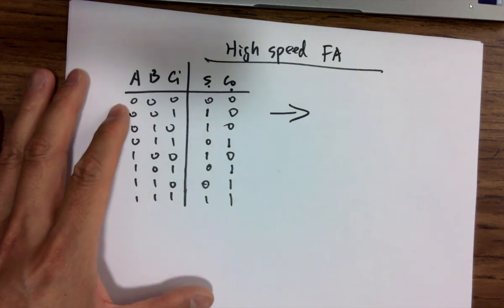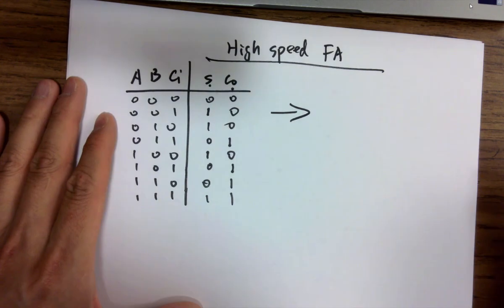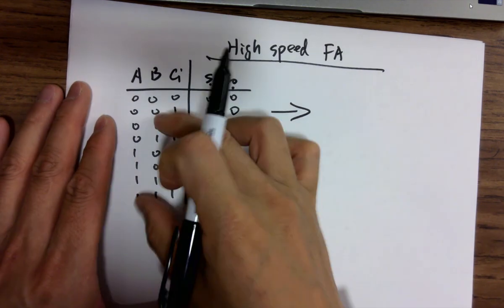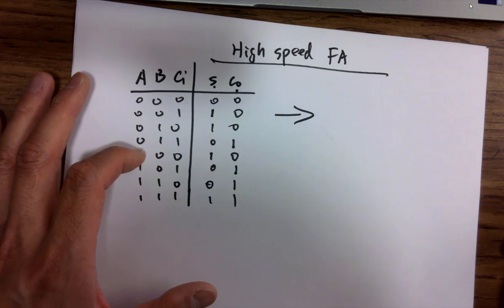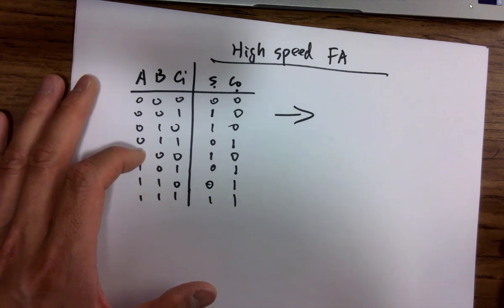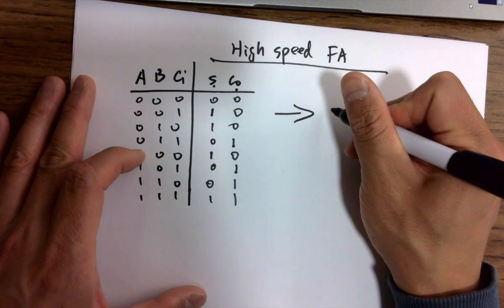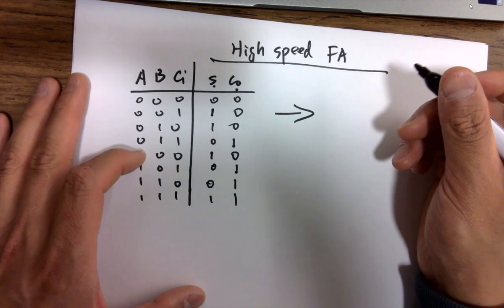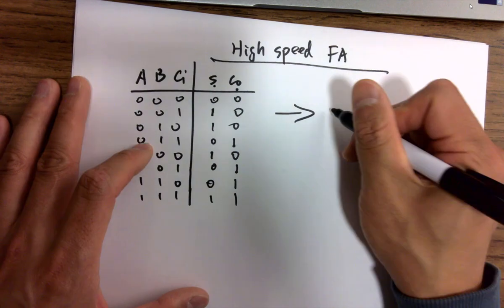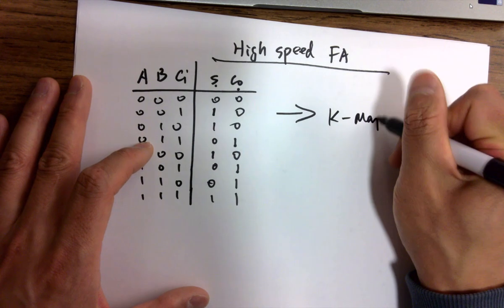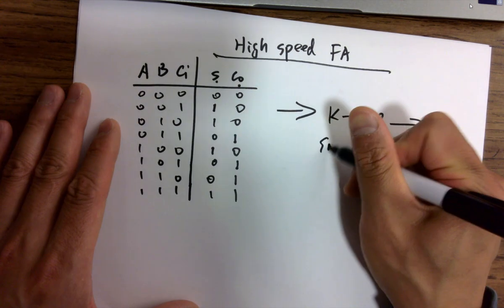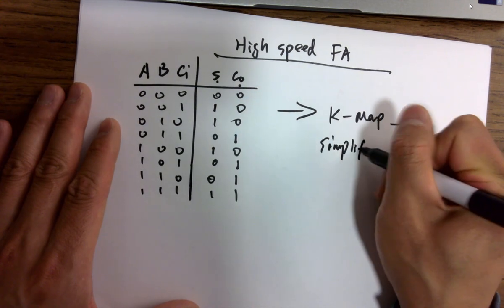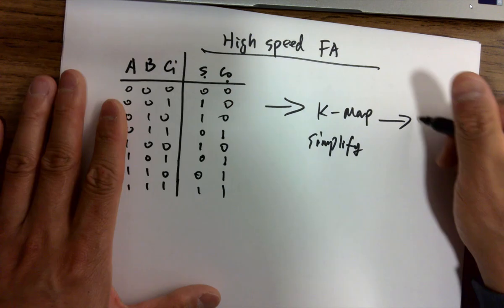So this is the original input. From here to the final chip, what are the steps? Just think about one simple digital block like the adder. What's the next? Translate that into a logic statement. Yeah, but before that, what do we need? A K-map, right? To simplify this a little bit. So from the K-map, we get a logic expression.